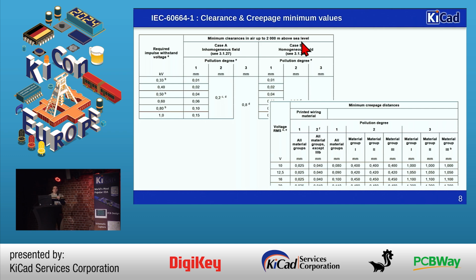What values do we pick? Basically, there's a table which is pages long that goes way beyond what I show you here, which tells you that for that much voltage, you should have this many millimeters of clearance or of creepage. I'd like to point out something. There are two cases, homogeneous and inhomogeneous fields. Homogeneous field does not exist. It's only between infinite planes or two spheres, the one inside the other. So basically, we're always in case A.